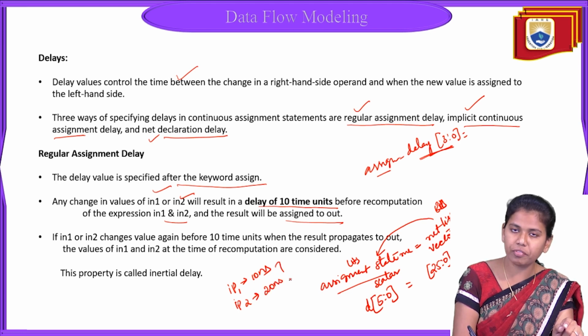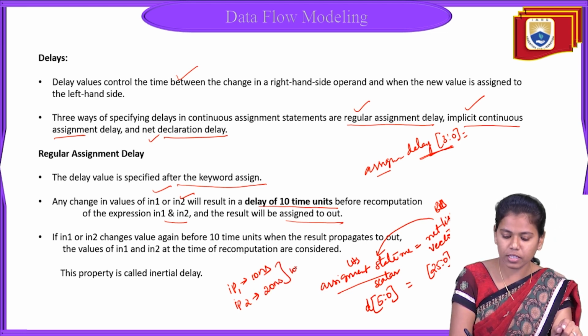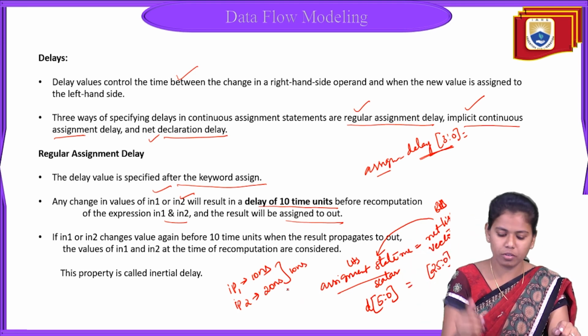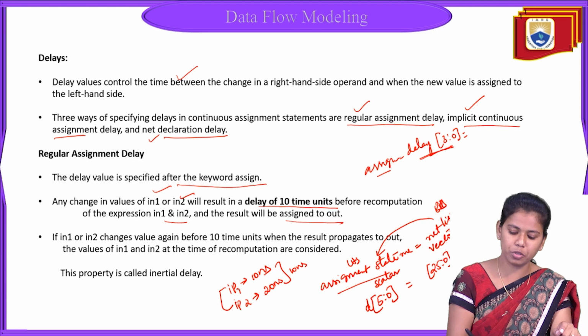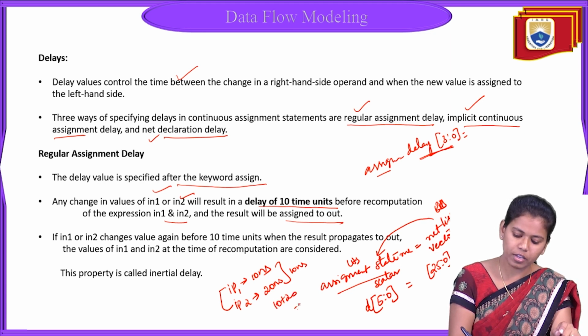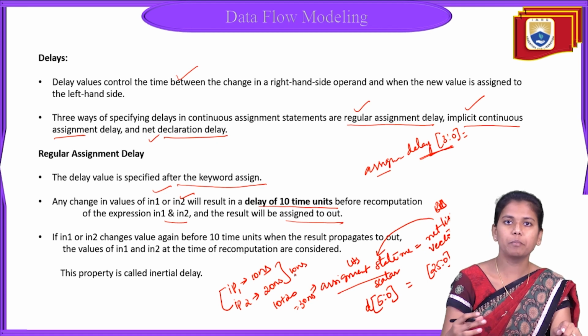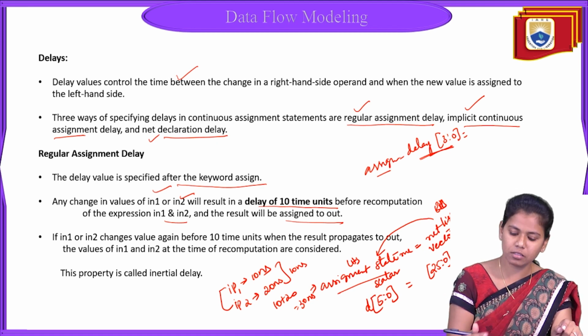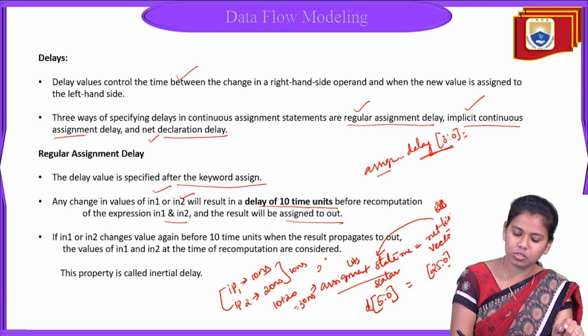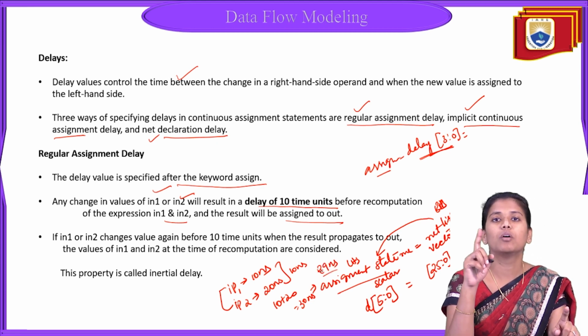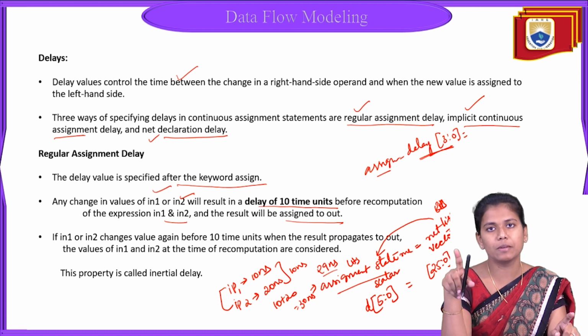The difference here is 10 nanoseconds. At the output, combining both inputs, 10 plus 20, we need to observe 30 nanoseconds. But in the process, due to some impairments, instead of 30 nanoseconds we see only 29 nanoseconds. So we are missing 1 nanosecond of delay.